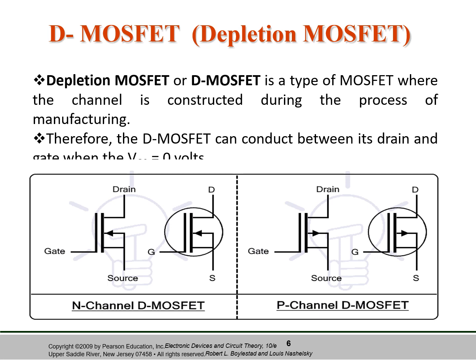Here you can make out there is a gap between the drain-source terminal line and the gate terminal, which indicates that the gate is isolated from the channel by a thin oxide layer. You don't draw this in a JFET; only for MOSFETs do you show a separation between the channel and the gate. This is drain, this is source, and for gate there is a small separation. For both MOSFETs, this is how you write the symbol. The arrow mark is different for N channel and P channel depletion MOSFETs.